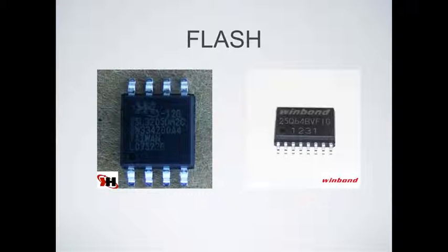Flash is a little different in that you don't have to supply this high value of current. It's easily erasable. Every time you want to write to the Flash, you have to do an erase before you do a write.